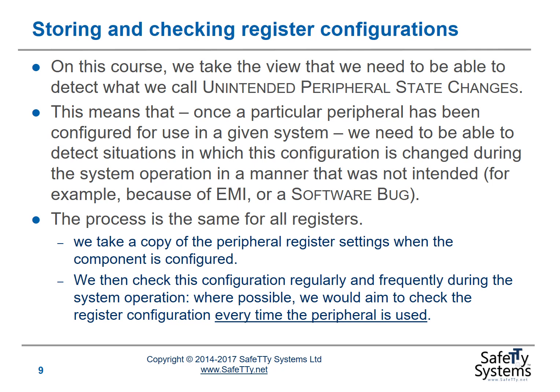And the process is the same for all registers. We take a copy of the peripheral register settings when the component is configured. We then check this configuration regularly and frequently during the system operation. Where possible, we would aim to check the register configuration every time the peripheral is used. So as I noted previously, if you have a look at TTRD205A, you'll find a complete example illustrating ways of checking the register configuration.